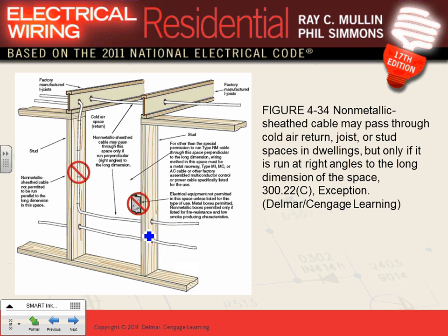Heating and cooling. Our interface with the heating and cooling system, guys, is a big deal. Number one, if it's the supply of the heat or cool, you cannot put anything in the supply. The ducts that supply heat or cool to the location. Now, the return, if you guys did dwelling, they sometimes use the 16-inch cavity as your return, right? They don't put ducts, they just use the cavity as return.